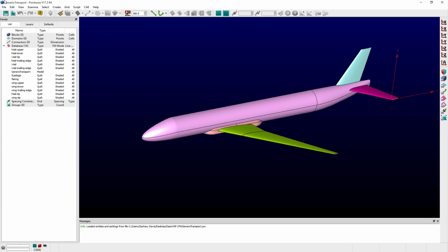One subtle advantage that models created in OpenVSP inherit, as opposed to those generated using more conventional CAD packages, is that the geometry surfaces are comparatively clean. There isn't a whole lot of effort required to prepare the model for mesh generation suitable for CFD or FEA analysis. You typically aren't going to encounter models with detailed design elements, gaps between surfaces, missing surfaces, or other common geometry anomalies familiar to FEA or CFD practitioners.